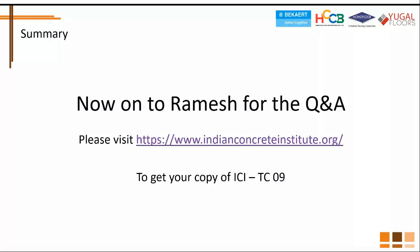Yeah. So one of the things which is also essentially given in the guideline as well is the need for expansion joint. Do we really need it? The fact is, for a typical industrial floor, you do not need expansion joints, especially in a country like ours, where any shrinkage in concrete is going to overcome any future expansion that you are going to foresee. This is typically seen on our sites, also validated over the last 40, 50 years, that the expansion pads lose contact from either edges of the concrete and the pad simply hangs in the middle. It's a common practice that we provide something like 15 to 20 mm of expansion pad, and at the end of let's say 9 or 10 months of the project, that gap becomes something like 30, 35 mm and the expansion pad is simply hanging, and that becomes a point where the joint edges start breaking when you have forklift movement or anything like that.